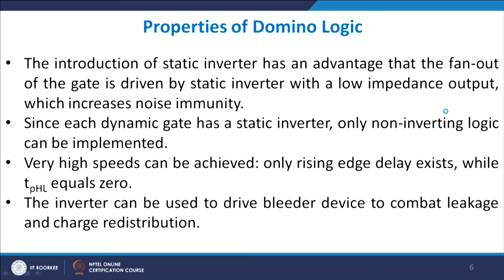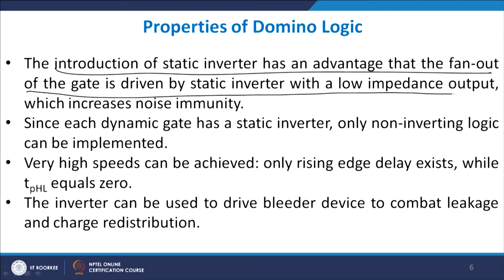So, as I was discussing with you, the introduction of a static inverter has an advantage: the fan out of the gate is driven by a static inverter, which is basically a low impedance node, and therefore increases the noise immunity. So, that is one of the important issues. Now, but you see the problem area.